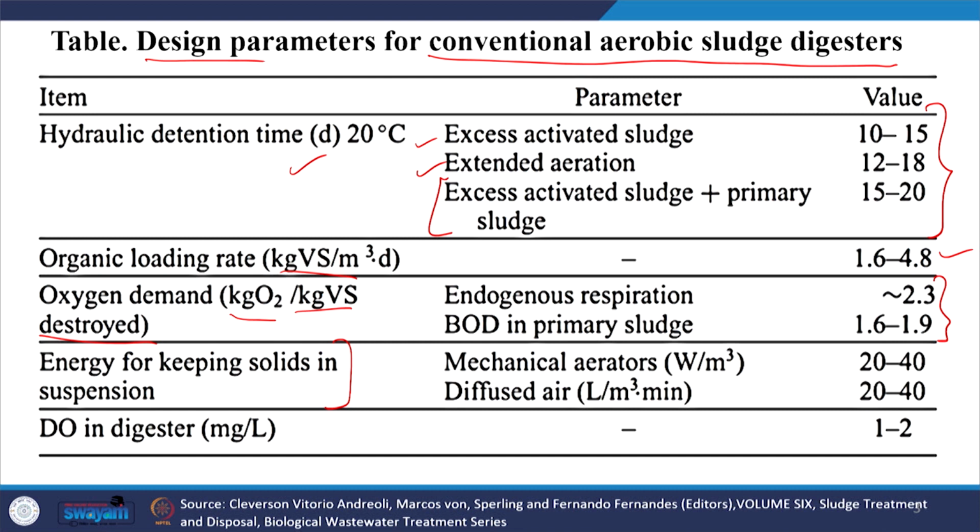Now, for the energy for keeping solids in suspension, that means keeping them in CSTR mode, mechanical aerators or diffused aeration may be used.